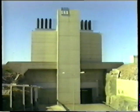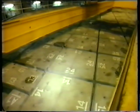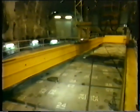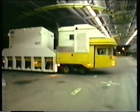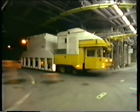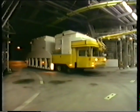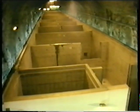The world's first deep underground repository is at Forsmark in Sweden, under the sea. It is used for low-level and intermediate waste. Containers of waste are placed in position with this remotely controlled truck. When the containers are packed in, the vaults will be filled with concrete. Then a thick cap of concrete will cover the top.